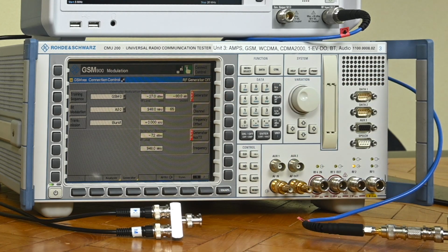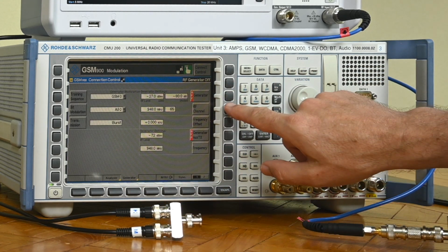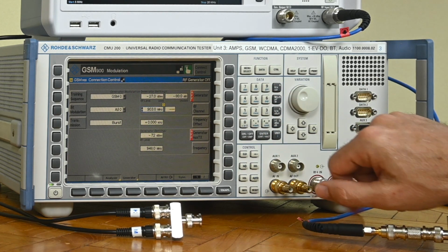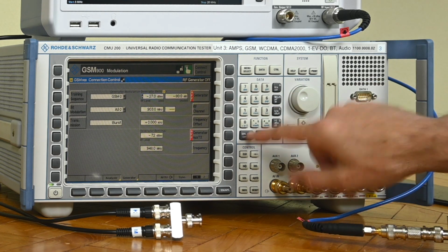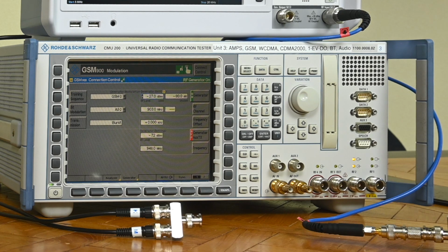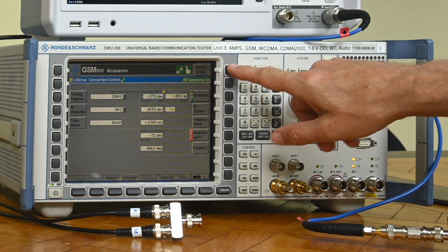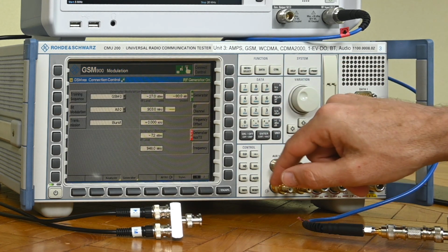But now we want the device to talk to itself. So what I'll do is, we had 903 here, so I'll fool it into having 903 megahertz here as well. That's one thing. The second thing I need to do is turn the generator on. I did that. Third, I want to check if input and output are connected. Now I send them to the same connector, so I'm fine there. So I'm almost there, but still getting no constellation plot. Why is that the case?